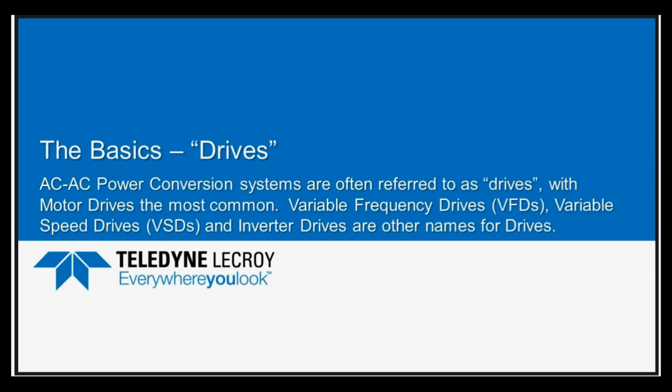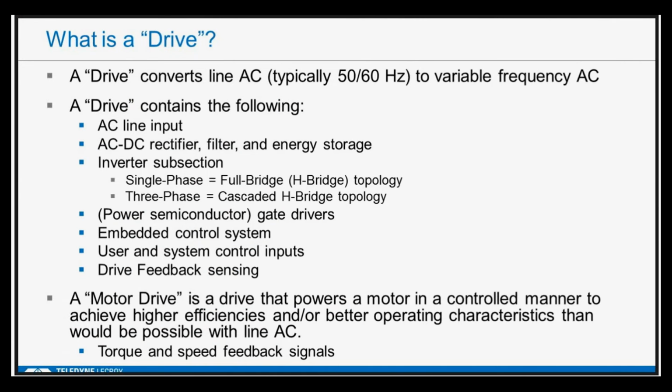Okay, so now let's talk about a drive. This is where everything comes together. The inverter subsection, that power conversion section, is one part of the drive. So what is a drive? A drive is really something that converts line AC, typically 50 or 60 hertz, or it could work directly from a battery as well, to a variable frequency AC output.